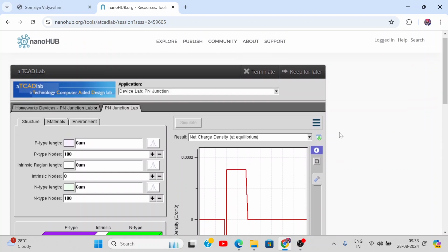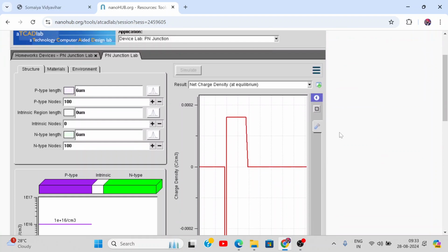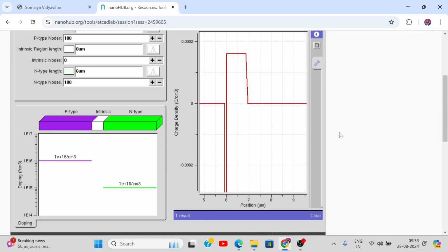Alright. So this is the way we can verify your answers, and actually you can see all the formulas which are intact. This is how you determine which type of junction we have, whether it is a P plus N junction. You see what happened over here? Which is higher, Xn or Xp? Xn is a little higher. So what does that mean? My N side is lightly doped, so the depletion region extends more over there. Whereas the depletion region on the P side is less. Why? Because it is heavily doped. On one side we have 1 crore, on the other side we have 10 crore. So definitely the depletion region will be pushed to that side.